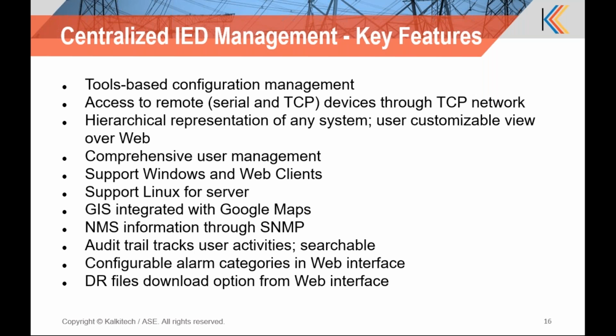Then it has a GIS integrated Google map, so all the live, communicating substations can be indicated over the Google map, and you can click on the corresponding map window, and from there further analysis and further download are possible. Then detailed network management is available, and this information is available through the Simple Network Management Protocol, SNMP.